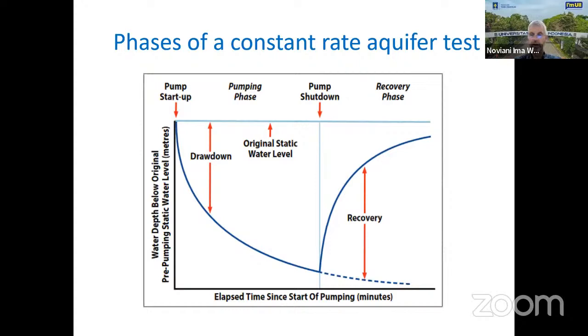It can be like 24 hours, 48 hours. I decide the test is over. I turn off the pump. What's going to happen? The water level inside the well is coming back up. So here you see the drawdown is going into reverse and the water level is rising. And if I wait long enough, it's again the same as the blue line here.